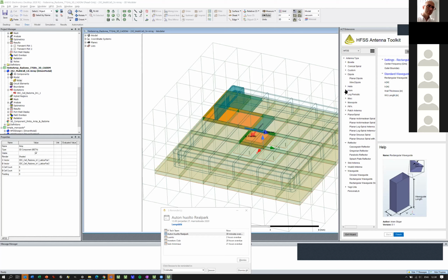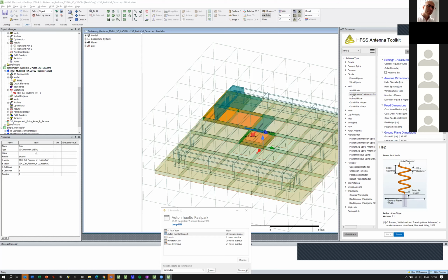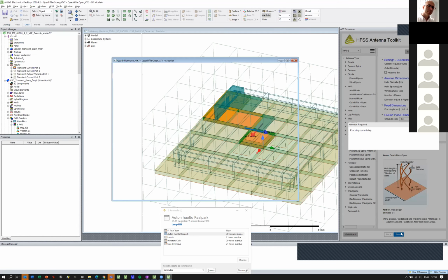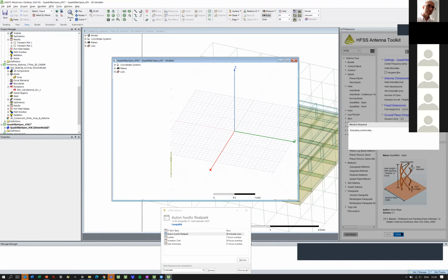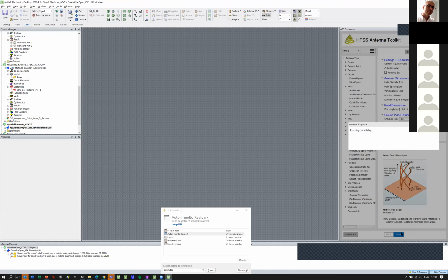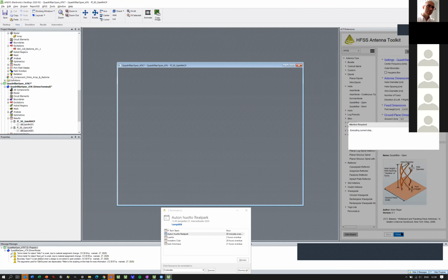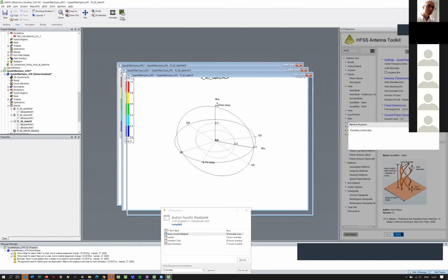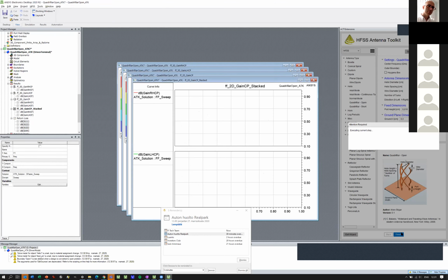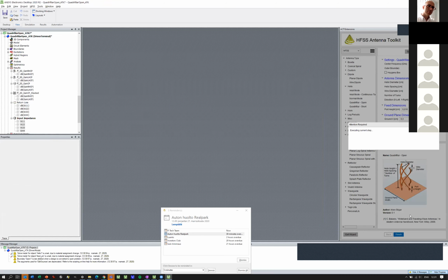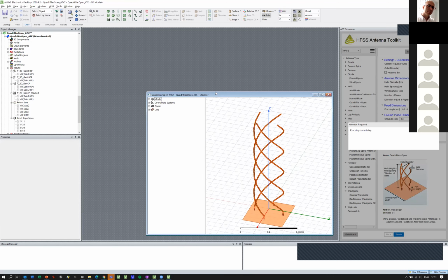Look, the horn helix. This is always nice. Yeah. So I can say that I want to have this 20 gigahertz and synthesize and finish. So I'm willing to have a helix antenna which is running at 20 gigahertz, and then the system will design it for you. Okay, it's not ideal. It's giving the best guess based on the analytical equations we can get for that.